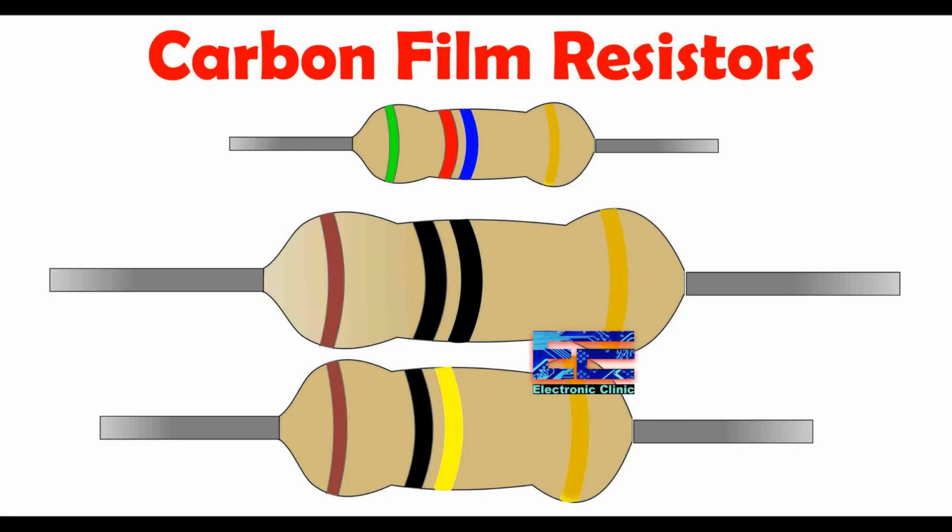Environmental stability: resistors can be exposed to various environmental conditions, including temperature extremes, humidity, and vibration. Stable resistors are designed to withstand these conditions without significant changes in their electrical properties. Moisture sensitivity: some resistor types, such as carbon composition resistors, can be sensitive to moisture and may experience changes in resistance when exposed to humid environments.